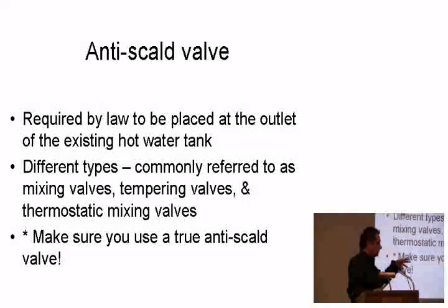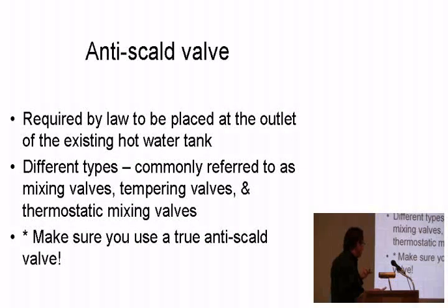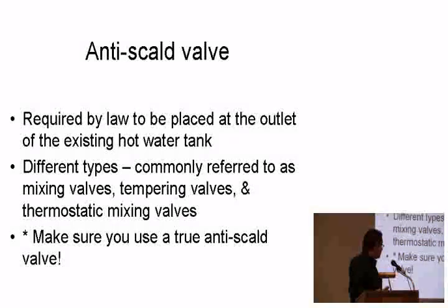If you get a solar thermal system put in, you have to have one of those put in if you don't have one already. There's different types, some that are referred to as tempering valves or thermostatic mixing valves. You want to make sure you get the true anti-scald valve. They're usually a little bit more expensive than some of the lower priced tempering valves, so you need to be a bit careful there. But a true anti-scald valve covers you under several conditions to prevent anything like that happening.